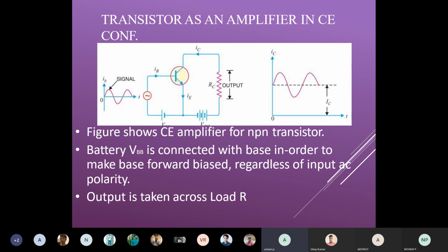And I am going to give the base current. Suppose I provide some base voltage, only then will the transistor become on. If it is on, current flow will occur from collector to emitter. If current flow is occurring, what will be your output? Will the output be less, or very high?